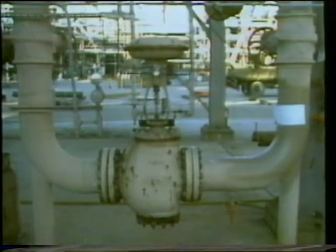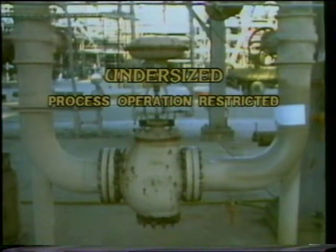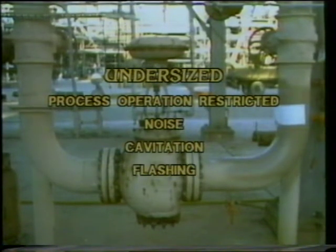The importance of correctly sizing a control valve cannot be overstated. For example, if this valve were significantly undersized, process operation would be restricted to low flow rates only. And increasing differential pressure to obtain higher flow rates could result in excessive noise, cavitation, and flashing.